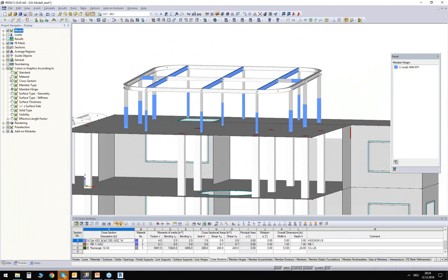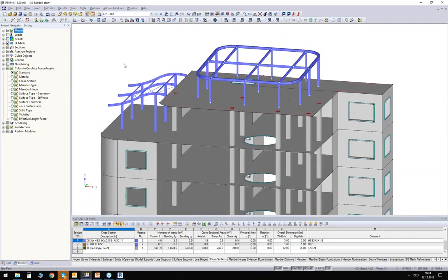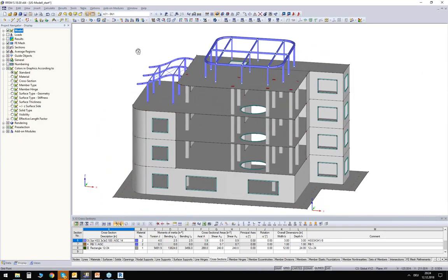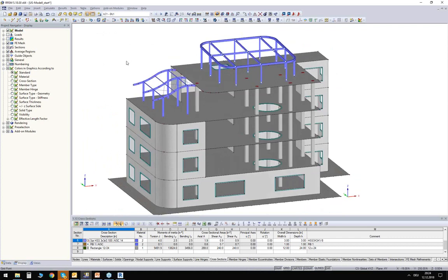Okay. So with the display navigator, we can double check, for example, the imported data. We assume the model data is now correct. So I want to continue with my loads. I have here 4 load cases. These are the 4 load cases I expected to have because I exported them from Revit.